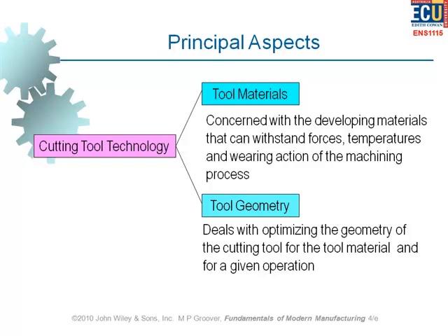Rigidity, which is directly related to hardness. What else? What's that? Roughness. Well, that's something which is decided, yes, by the geometry of the workpiece. That's relevant to geometry rather than the material. Inertness. We don't want to see the material of a cutting tool which is making a chemical reaction with coolant or the workpiece itself.